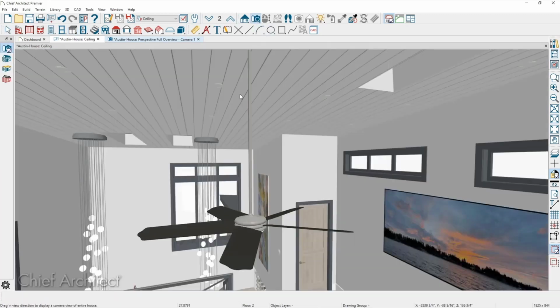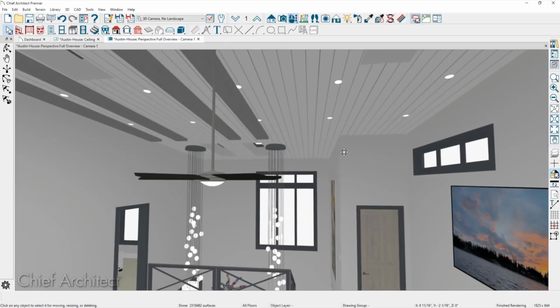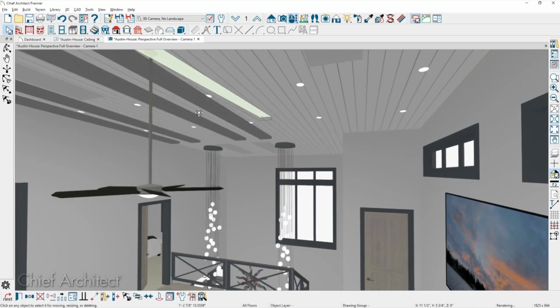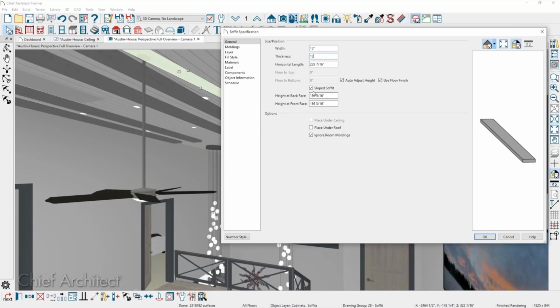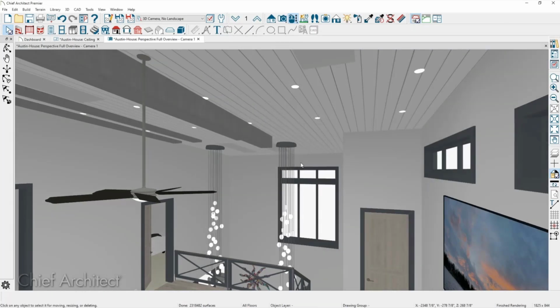And then we go in and we look inside here. I didn't make very big ones. And then you have to make sure you have the electrical layer on and whatever else so that you can do that, right? Right. So to make a taller beam, you just go in there and adjust the dimensions of the soffit? Yeah, I just used a pretty thin soffit. If you open these up, currently my thickness I set to be 12 inches, then you'll be able to poke that down a ways. There you go. So soffits follow roof or follow ceiling, depending on how you have it set up.